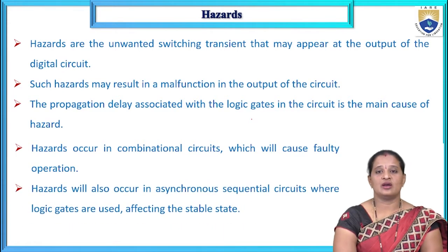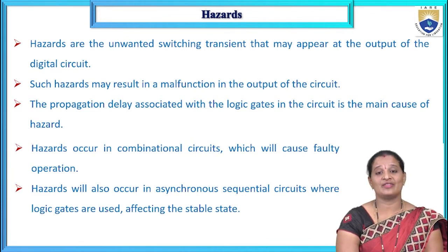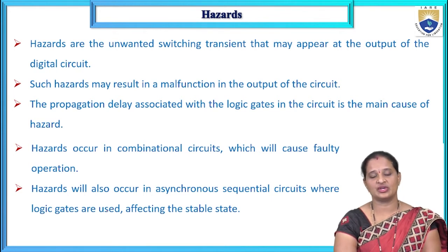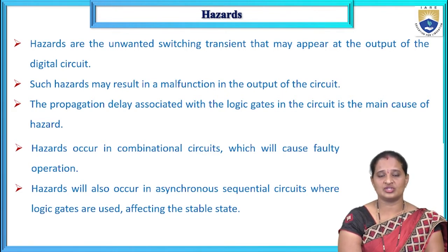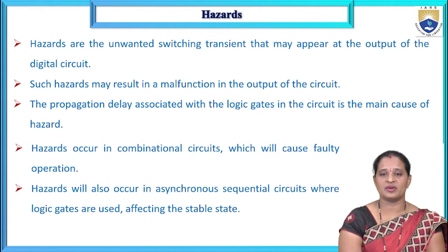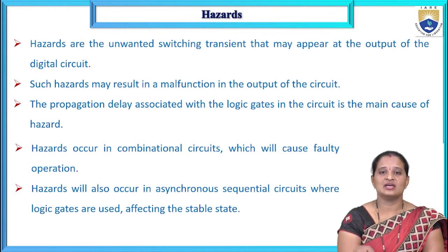Next, hazards can also happen in asynchronous sequential circuits where logic gates are used. In an asynchronous sequential circuit, along with the flip-flops, we also use some extra logic gates. Due to the circuit formed by those logic gates, we may also have hazards in asynchronous sequential circuits, which may affect their stable state.